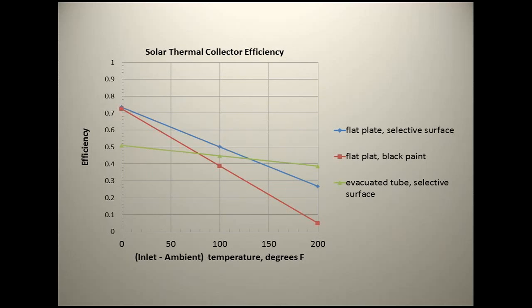But the basic idea is these tubes are very good if the water coming in is very hot, or you want to produce very hot water, or you're in a really cold climate, where it's minus 40 out, and so the losses going out of it are really important. Then tube collectors really work well. So it's like process water. If you're running a dairy, you want 160-degree water, you always want really hot water. So tube collectors would be better.